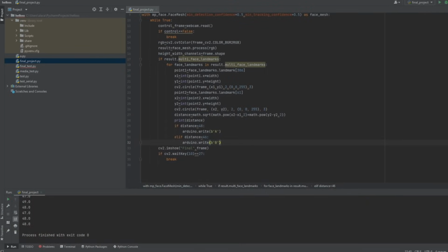So, how can we fix this error? Actually, fixing this error is very simple. For this, it will be enough to make a small addition to our Arduino code. What we need to do is to clear our LCD screen before the setCursor function in our conditions. In this way, we can achieve the desired result.